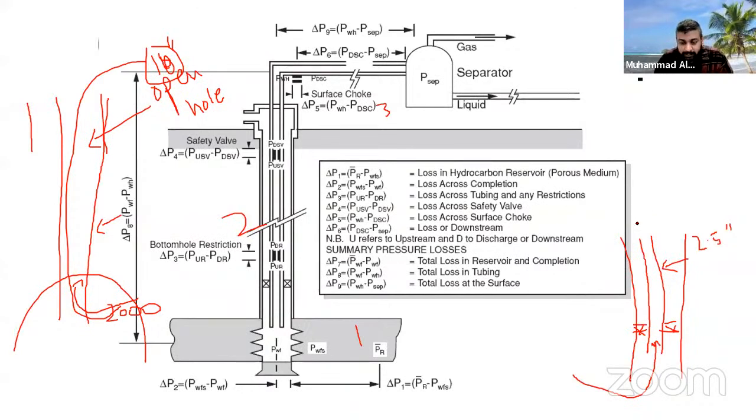Well test engineers usually have a separate domain. Well testing engineers have all of the testing data, and production engineers need the well test results when you do workover jobs. For example, if there's a formation damage, you do the well test, because well tests tell you the skin factor. And the skin factor is a very valuable thing that you need for production engineering evaluation, or for production forecasting.